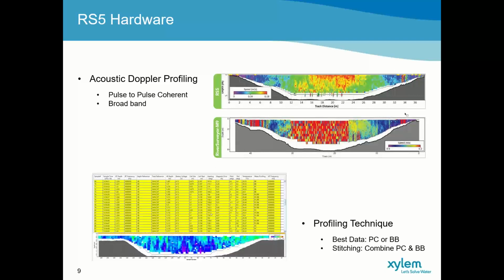This is an excellent tool for especially low flow measurements and shallow measurements, because it is improving the measurement accuracy of your measurement cells closer to the water surface, theoretically where your highest velocity occurs if your channel banks don't impact the velocity distribution. It's also a unique tool to use for methodologies that focus on surface velocity measurements, because you can really now focus on those top layers to get a very accurate surface velocity measurement.